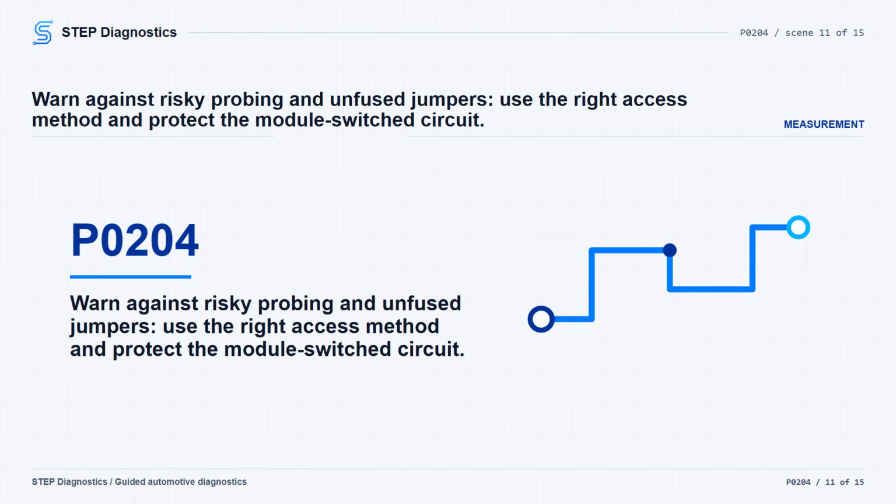Back probing is only for situations where the circuit must be tested under actual operating conditions, or where voltage drop has to be measured with the circuit operating. It is not the right test for a single-point voltage check when 0 volts is a possible result, because you cannot tell a bad probe contact from a true 0-volt result. It is also not the right test for continuity or open circuit checks with an ohmmeter between 2 points. In those cases, disconnect and isolate the circuit and test normally.